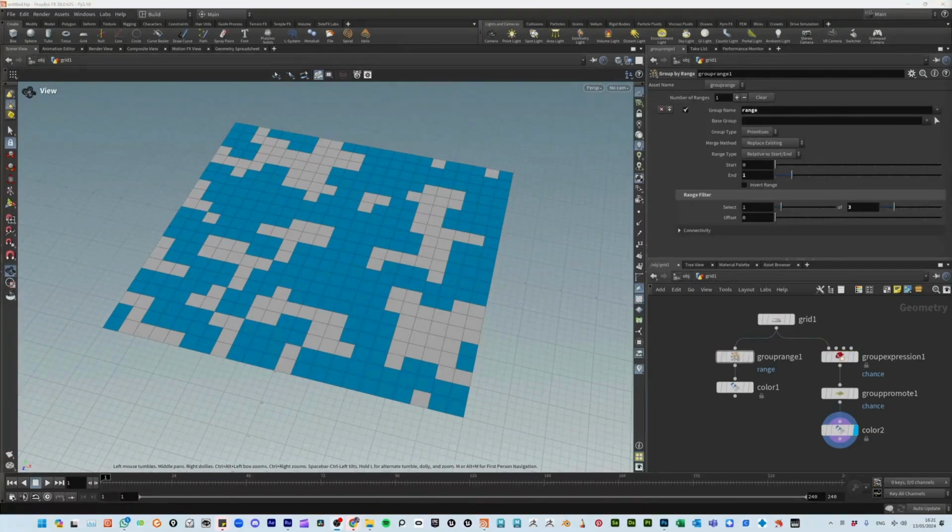As you know, we like to give a challenge exercise at the end of each topic. Create a Houdini network that incorporates curves, geometry, and colors to build basic objects. Use the techniques that we saw here to build your network. Try using geometry primitives like sphere, cubes, grid, also the tools that we saw to create curves and lines, to build basic shapes. You can color each one. You can combine objects by using the merge node.